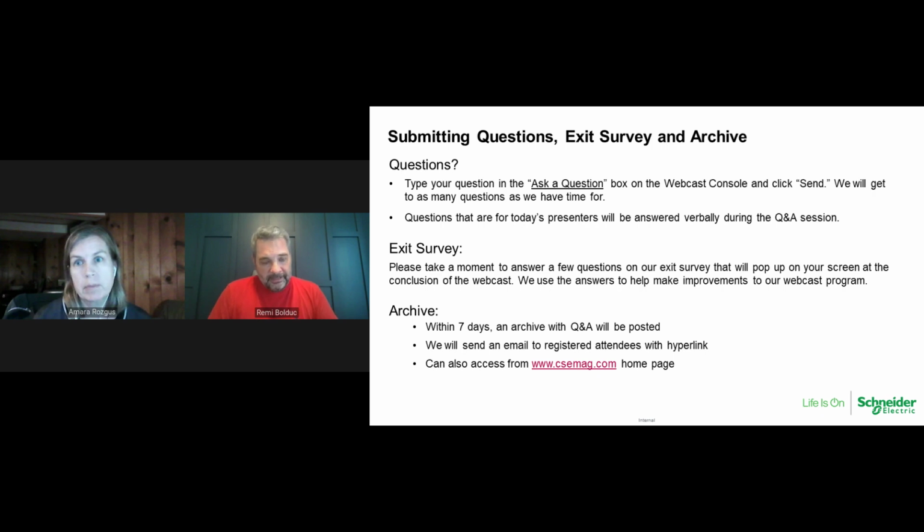Good question. Let's say if we go back in time, in the old days, 25, 30 years ago, making me feel old, but anyway, they used to use a bank of inductors to inject inductive VAR in a system. But this tends to be abandoned now. What is used today is mostly active harmonic filters that have the ability to inject leading or lagging VAR in a system that can correct power factor in both directions. And typically this is what is used.